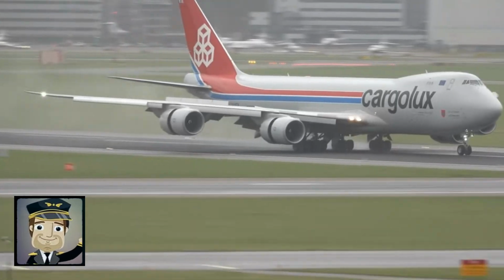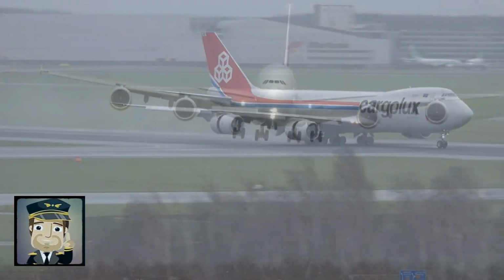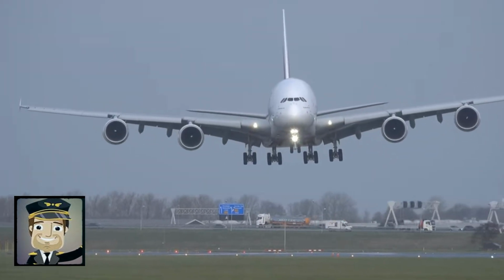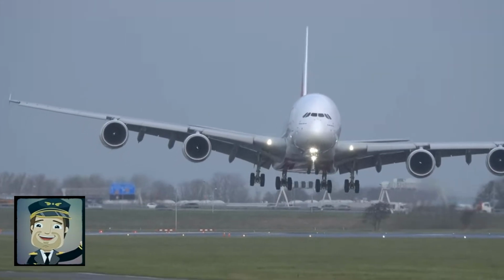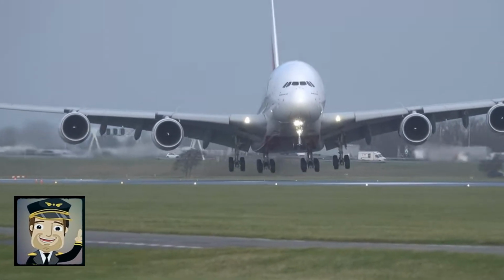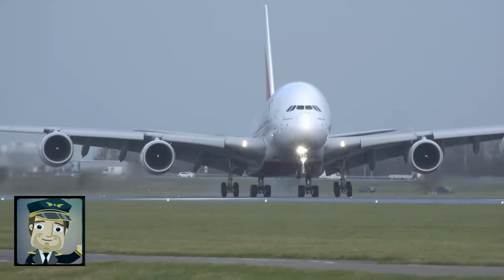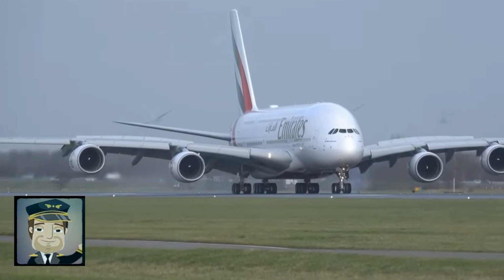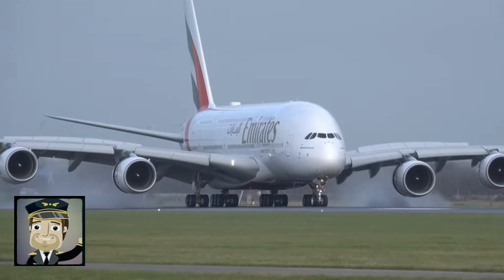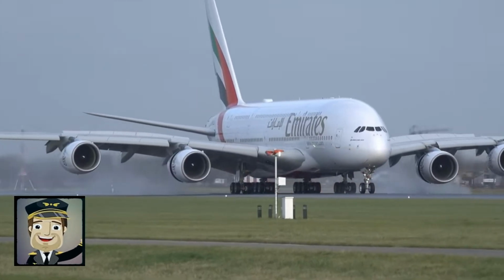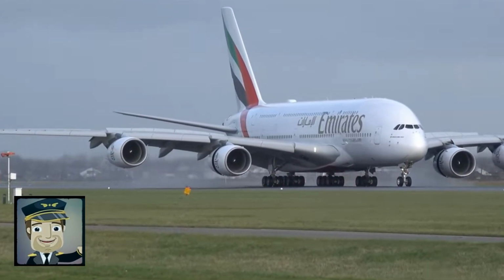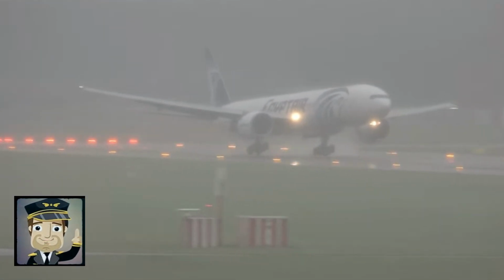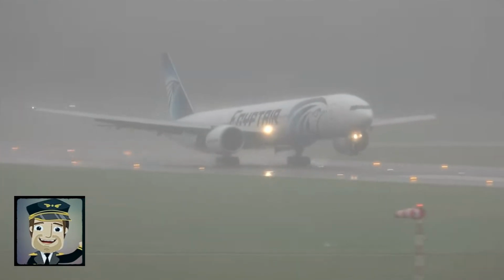The wing low or side slip technique, on the other hand, is widely used in smaller aircraft and in pilot training. In this maneuver, the pilot keeps the aircraft aligned with the runway from the start of the approach by banking the upwind wing slightly into the wind and applying opposite rudder to counter the drift. In this way, the aircraft remains aligned to the runway axis throughout the procedure. This technique demands greater coordination, as the pilot must simultaneously control bank angle and rudder. While very effective, it can cause discomfort in larger aircraft, where excessive bank angles may compromise passenger comfort and even